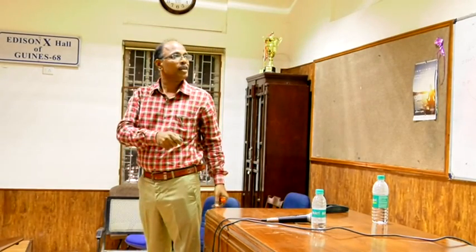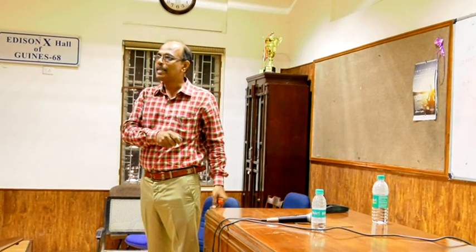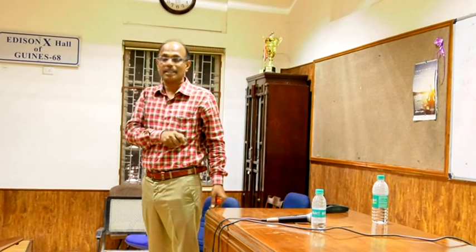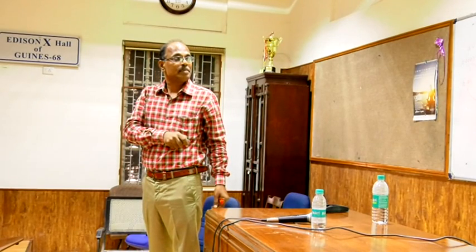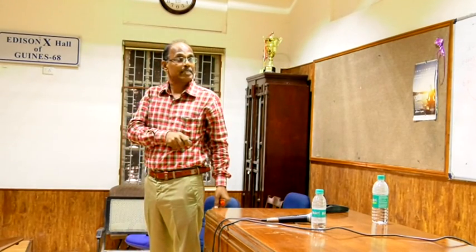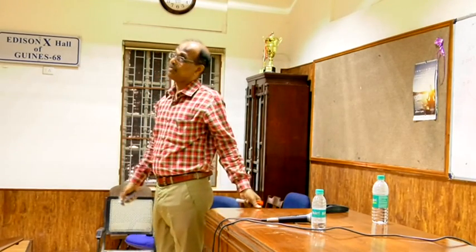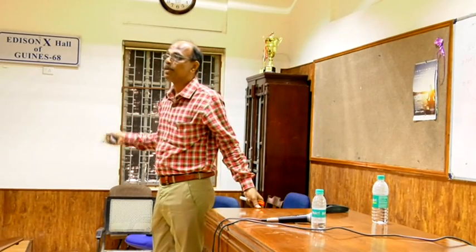So we have to find only the mismatch and multiply it with the already available inverse matrix. The inverse matrix times the mismatch will give the correction. Similarly, the inverse matrix times the mismatch will give the other correction. These are repeatedly solved, so this is very fast. That's why it's called the fast decoupled power flow method.